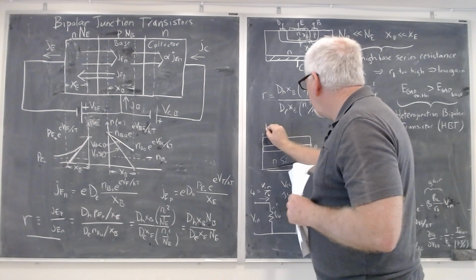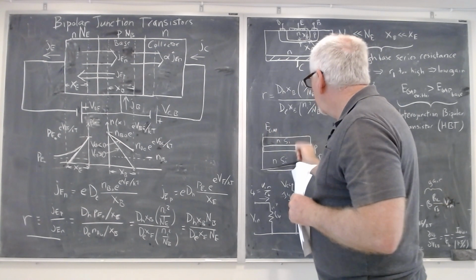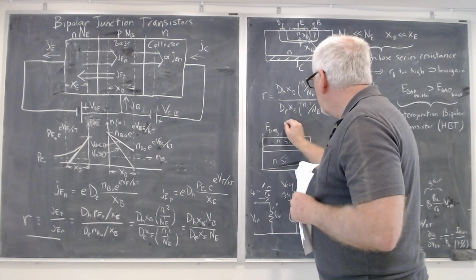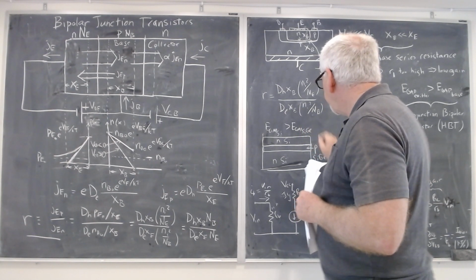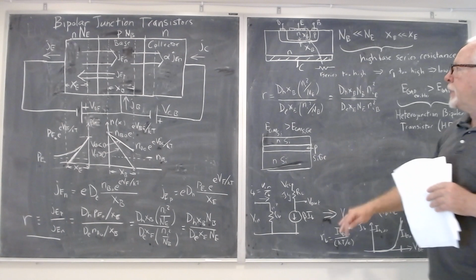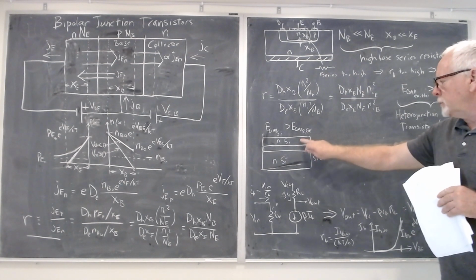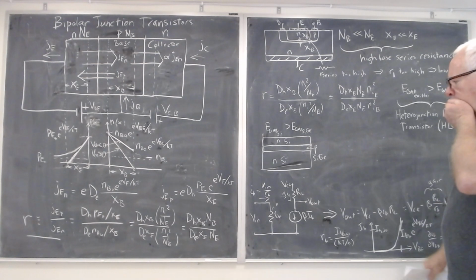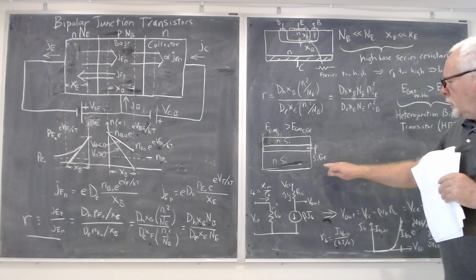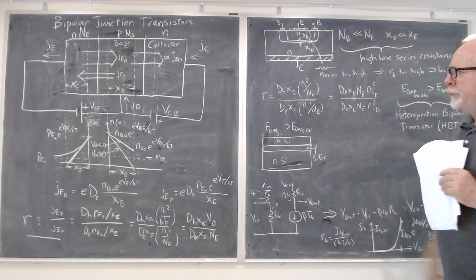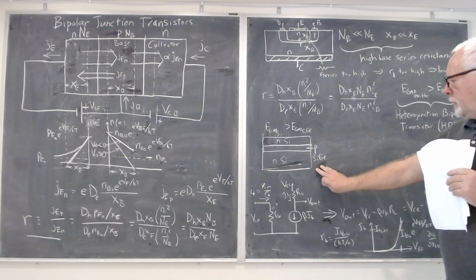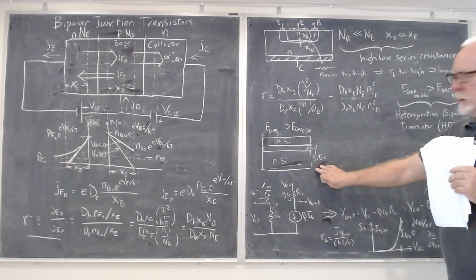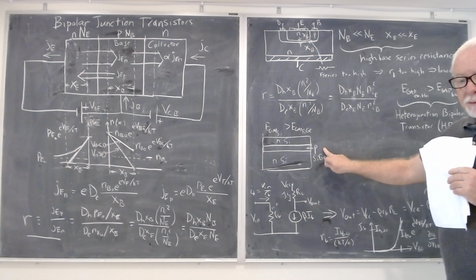And the band gap of silicon is greater than the band gap of silicon germanium. So you basically make it by epitaxy instead of diffusion so that you can have dissimilar materials here. Silicon germanium, there's other materials you can use. These are what's called group 4 materials. And the advantage of making it using group 4 materials is that this can then be integrated with CMOS.